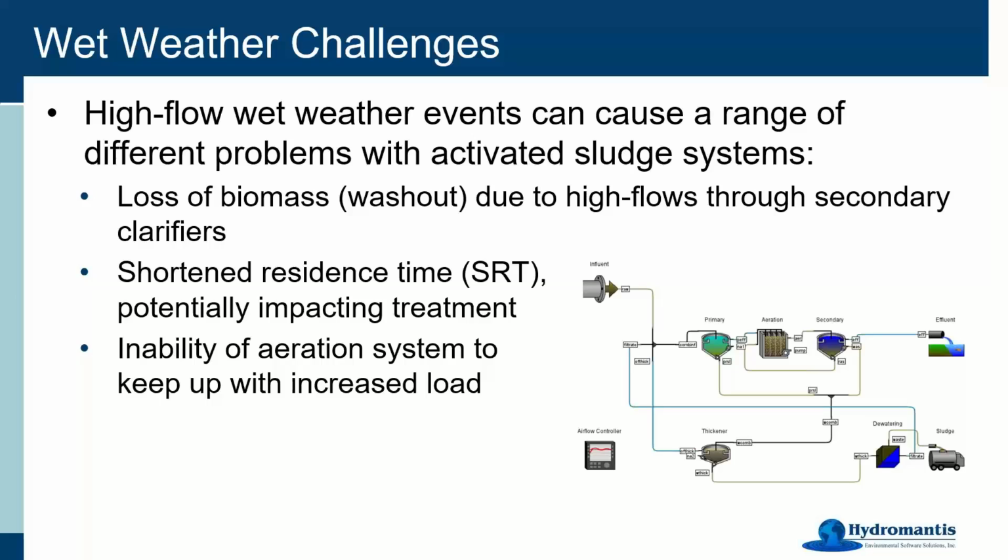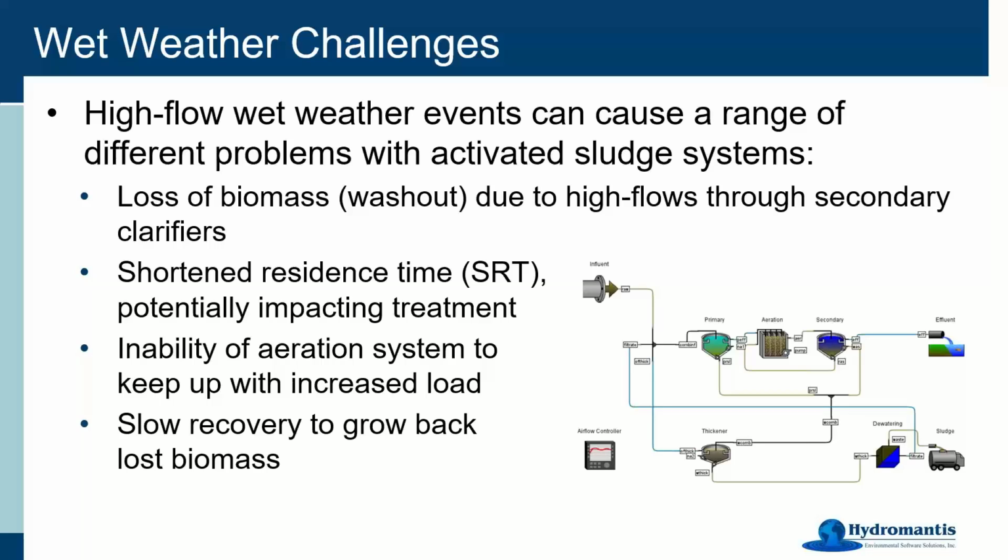A lot of places where there's going to be a high flow and potentially a high load come into that system can also make for challenging oxygen supply. So you may find that there's a lot of aeration requirements coming in with that higher load, and your DO control system wants to push more air in there, and so you may find that the high flow is presenting more loading than you can supply the air for, and that can be a big challenge there as well.